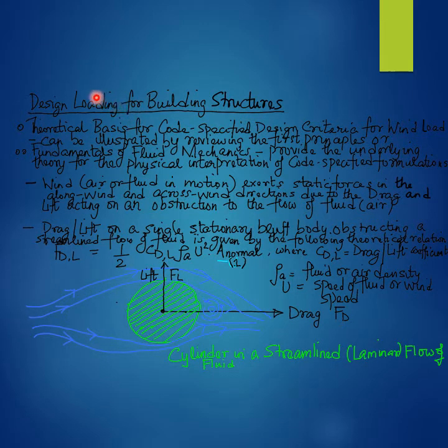We had mathematically derived the theoretical formulation for the maximum or the peak value of the theoretical dynamic seismic base shear, V subscript small b, expressed as a function of time, based on the dynamic equilibrium equation formulated for a single story frame model with a single degree of freedom.